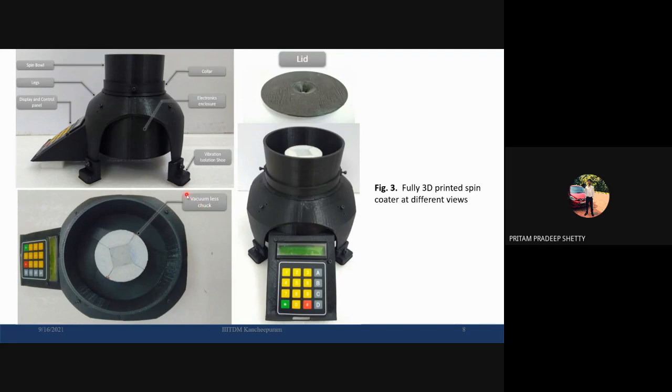And then we talked about vibration isolators. Here is a vibration isolation shoe which will incorporate this sponge, which is a porous structure. As I told, this vibration isolator should be placed strategically throughout the structure. We place it on the foot as well as near this display and control panel, so that the overall vibration doesn't get transmitted to the table and your whole table doesn't start vibrating.